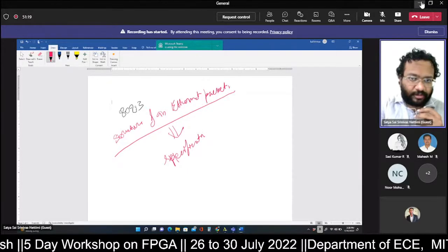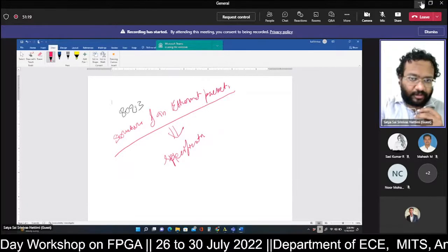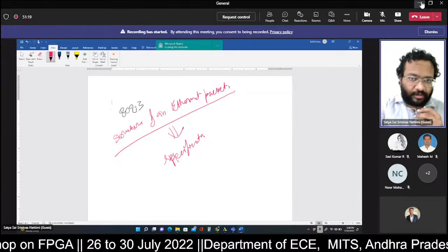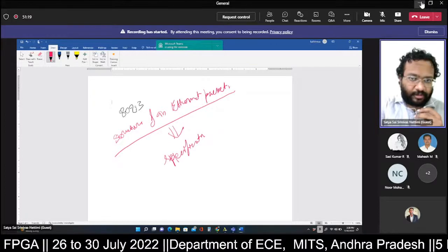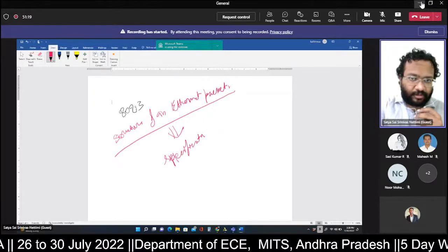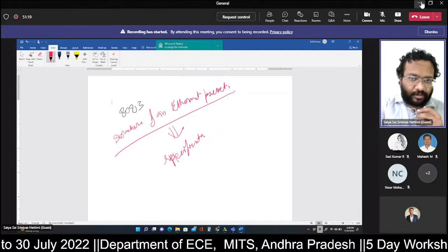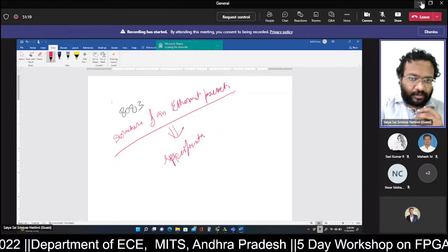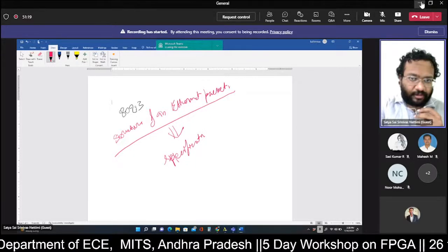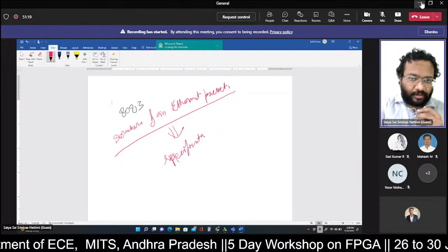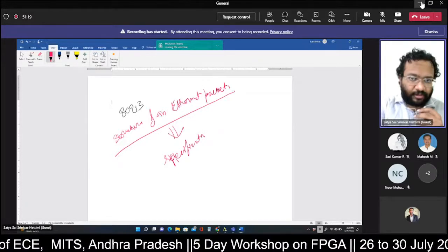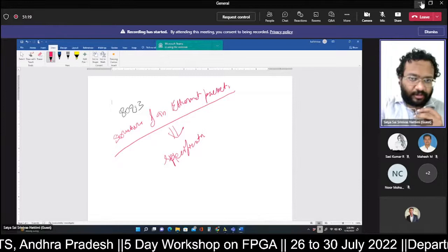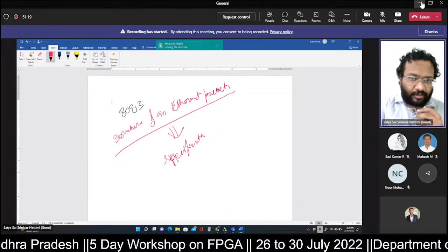So the sequential state register logic, that is the present state logic, as the name suggests, is sequential. It is dependent on the clock. We will do sequential state register logic and combinational next state logic, these two, using the behavioral level of abstraction. In behavioral abstraction, we use procedural statements, and wherever you use procedural statements, you have to use always blocks. So always at, in the sensitivity list, I will give the sensitivity to clock, the positive edge of clock.